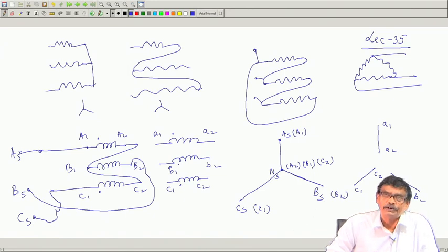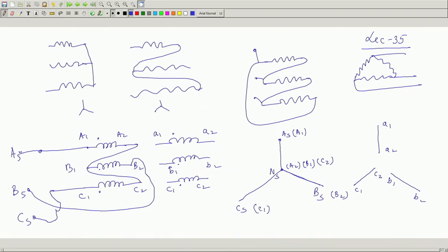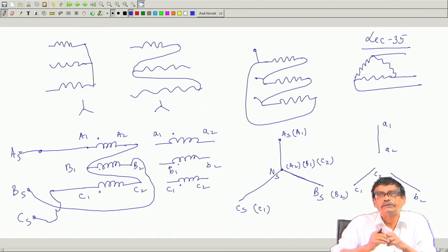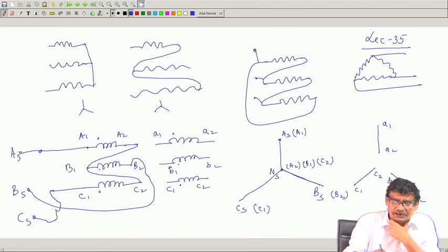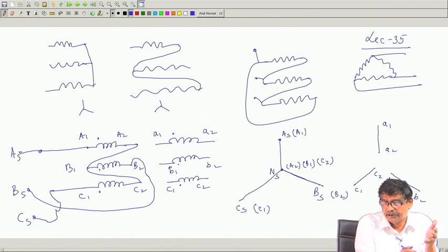Okay. Now the point I want to make is, without doing polarity test, you should never try to connect the 3-phase transformer either in star or delta, and the difficulty that will come, that I am telling. Somebody connects like this, although the actual polarities are like this, but he does not care, star connection, okay, connect supply.